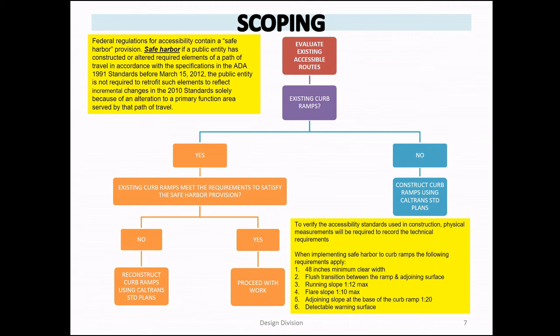And there's a difference now from the old days on new construction, where we were allowing contractors to use the cast in place and the bolted detectable warning surface. Now, if it's brand new construction, it's just cast in place. But if you're just retrofitting, then you can just do the detectable warning surface, which is bolted.